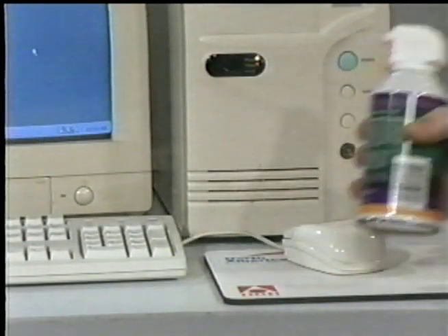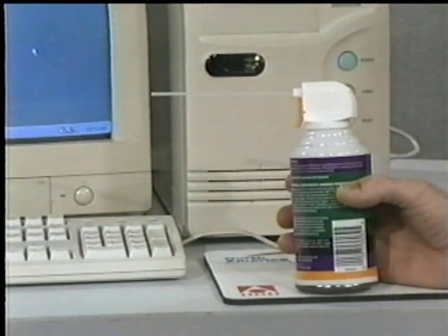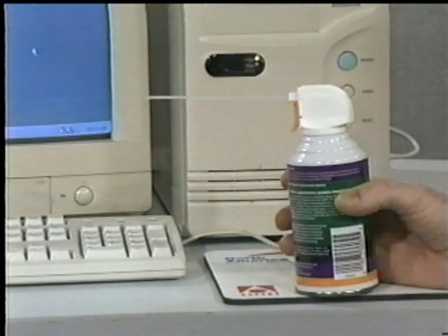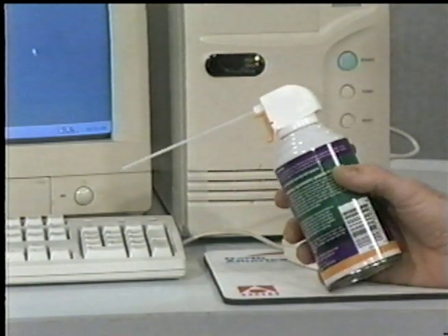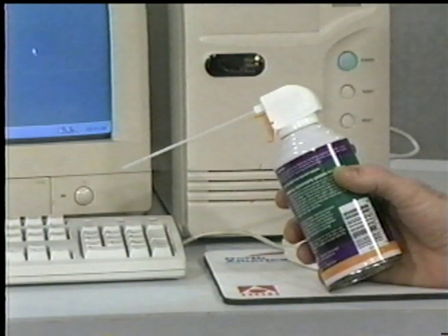Chemicals can be used to help clean, troubleshoot, and even repair a system. One such chemical is freeze spray. These sprays are used to cool suspected failing components quickly so as to restore them to operation. This substance is not used to repair a device, but to confirm that we've found the failed device. Often a component's failure is heat-related, and cooling it temporarily restores it to working order. Another very useful chemical is compressed air. Compressed air is used as an aid in cleaning. Normally it is used as a blower to remove dust and debris from the keyboard and mouse.